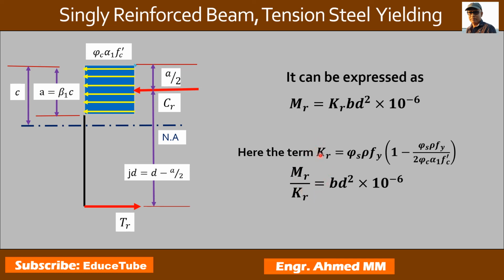And the Kr value we can find from the table, it is A3 in CSA A23.3. From that table we can get the value of Kr for various concrete strengths and reinforcement ratios, for the common case of, say, Fy equal to 400 MPa.